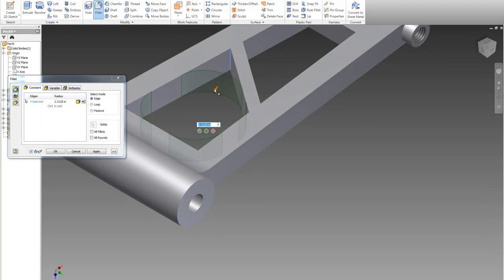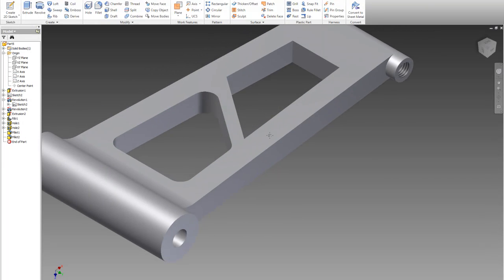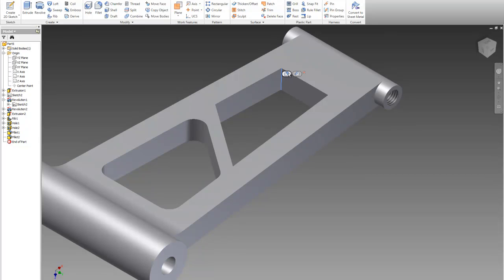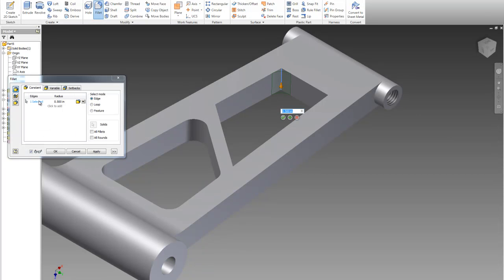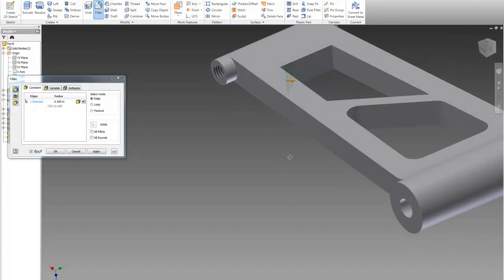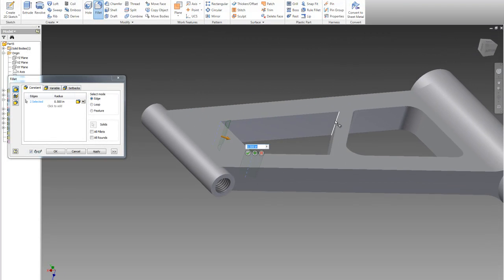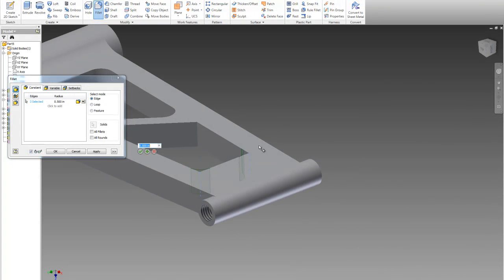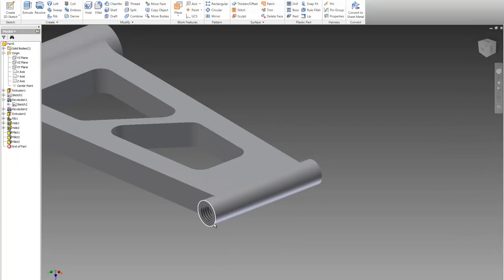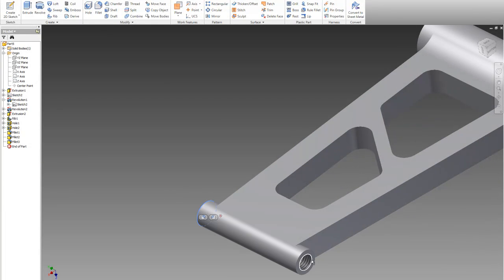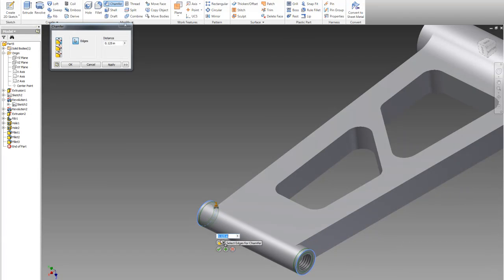Also, you're going to notice here I can actually select multiple edges. Just hold down your control button as you're selecting your edges and then select your fillet tool. If I forget to hold down the control button, I select the edges, just go right into my box and select the select tool, which allows me to go in and continue to select those edges for that fillet. Noticing when I'm selecting these edges, I have that arrow there. When I push and pull it, it actually snaps to different dimensions. We'll take a look in a minute here at how we can change what that snaps to.